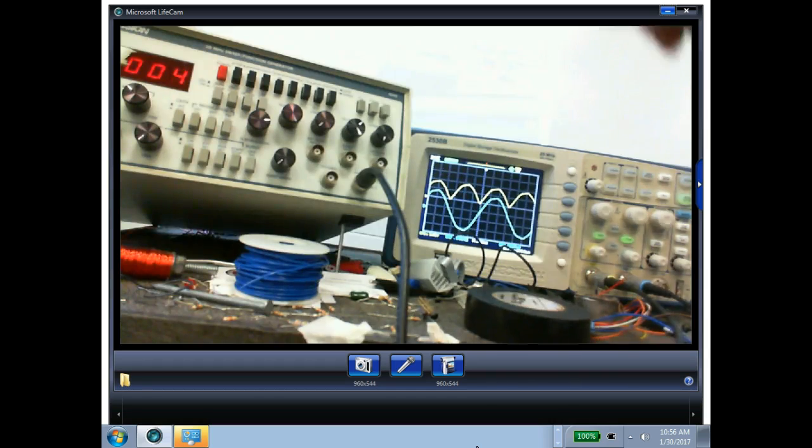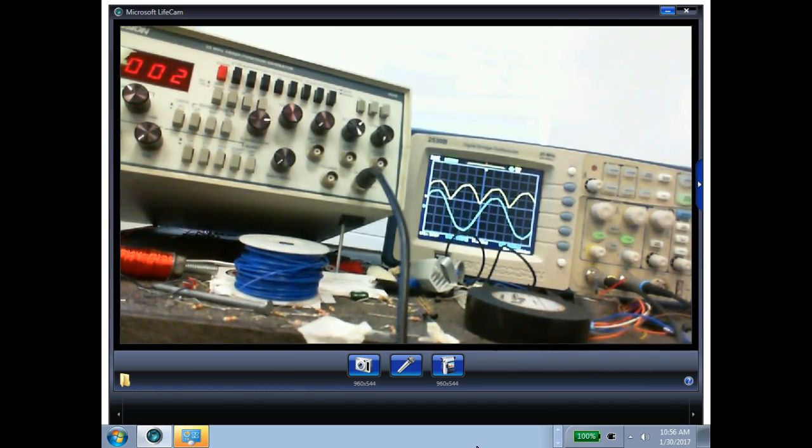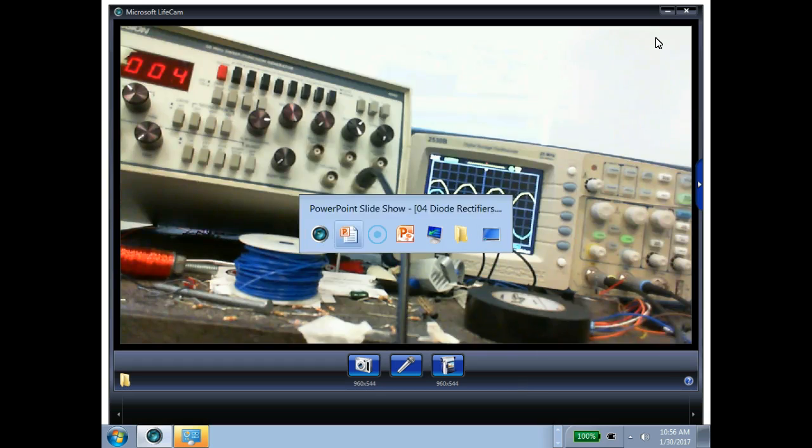So what we're saying is that for every cycle of our AC, we get 2 cycles of our DC. So full wave. So we use these guys all the time. Every charger I've ever seen does that. It's usually a full wave center tap. That's what it is. So if you got a lead acid battery charger, you put a scope across it without it hooked to the battery, this is probably what you see. Are we okay? Full wave center tap. Let's hook our motor up to it.